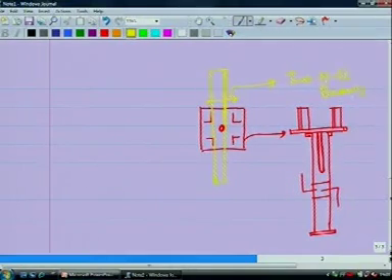This spacing can accommodate 2 H16 beams. So, the advantage is that in case you find that the length of the H16 beam is not adequate, you can lap them. So, one H16 here, another H16 here, they are simply touching each other, that is it, and they are on the four-way head. Is it clear to you?